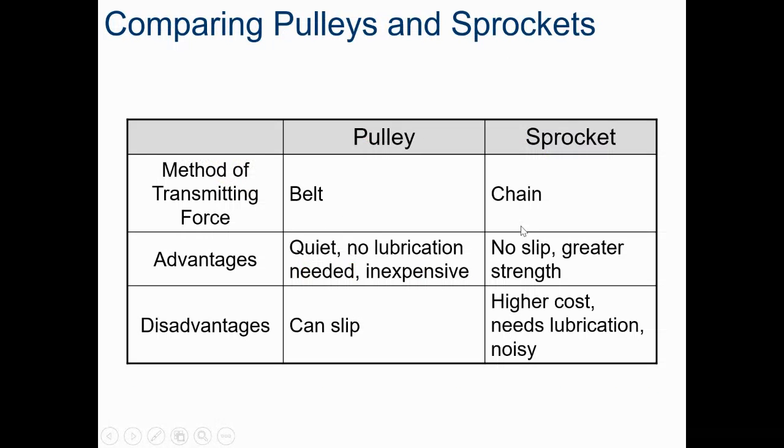Okay. All right, so just a quick comparison between the difference between a belt and a chain system. Why would you choose one versus the other? There's definitely places where one is better than the other. Just within what we have at the academy, our drill press is actually a belt-driven system, which is kind of interesting. It takes from the motor and it uses a compound belt system. It's got two sets of belts to change the ratio, the speed and torque of the output.